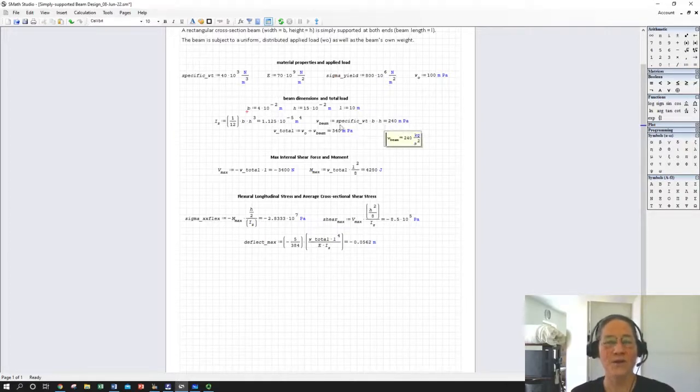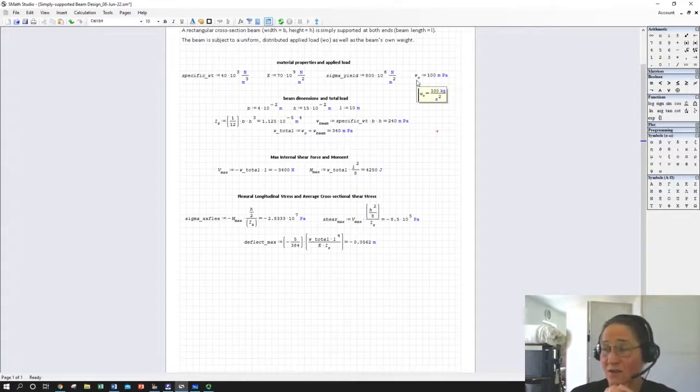And what we're seeing as we change these two, the more we change the base and the height, the bigger we make them, the bigger our dead load becomes in this case, even with a lighter material. So that's an example of why an interactive design guide is important, but also just a general knowledge of what things are linear, what things are squared, what things are cubed.